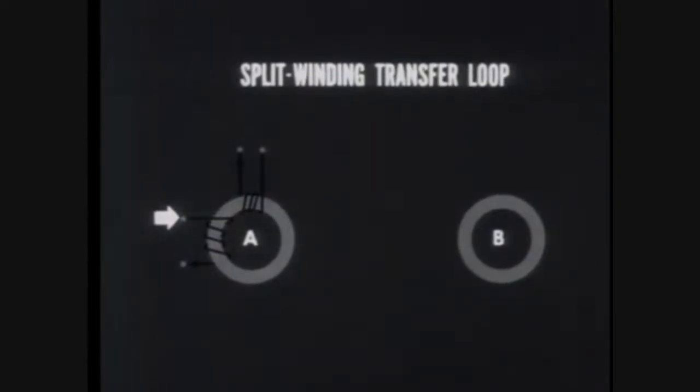This is the one that our logical diagram showed as coming in at time t0 and setting core A to binary 1. At the top, current comes in on the dot side, setting core A to binary 0, and the time is t1. There is also an output winding at core A, and like those in the single diode loops, this output has more turns in it than the input windings have.